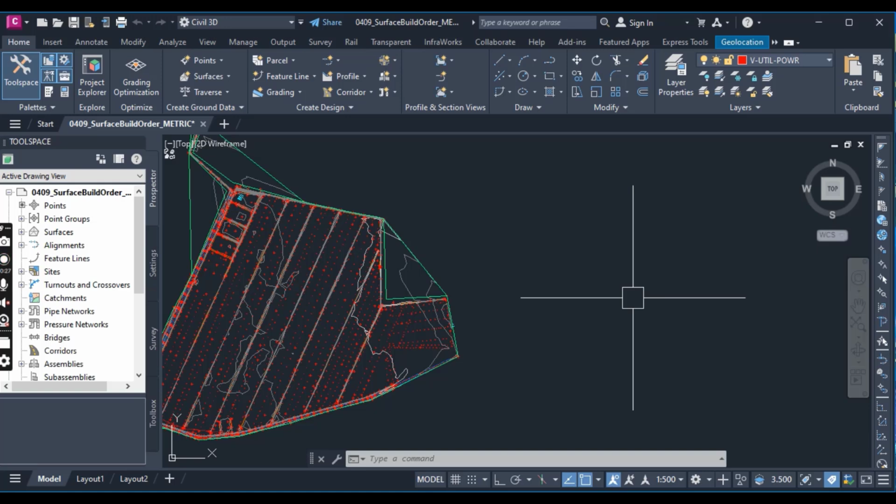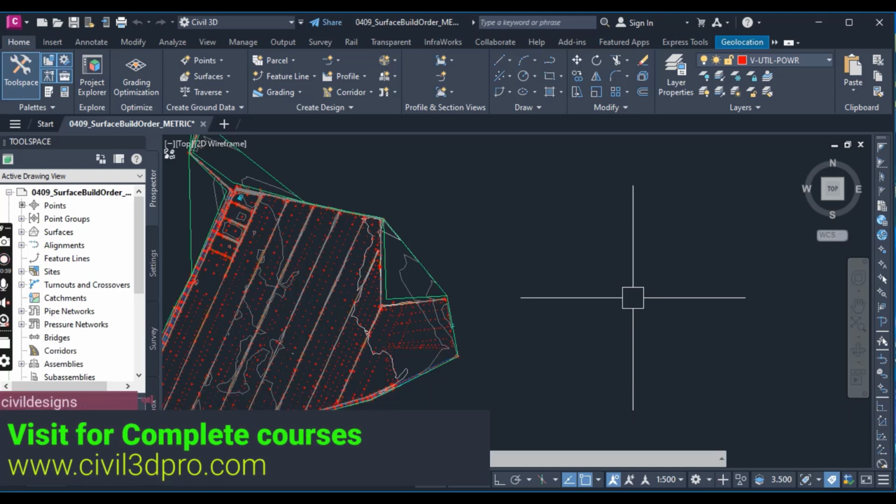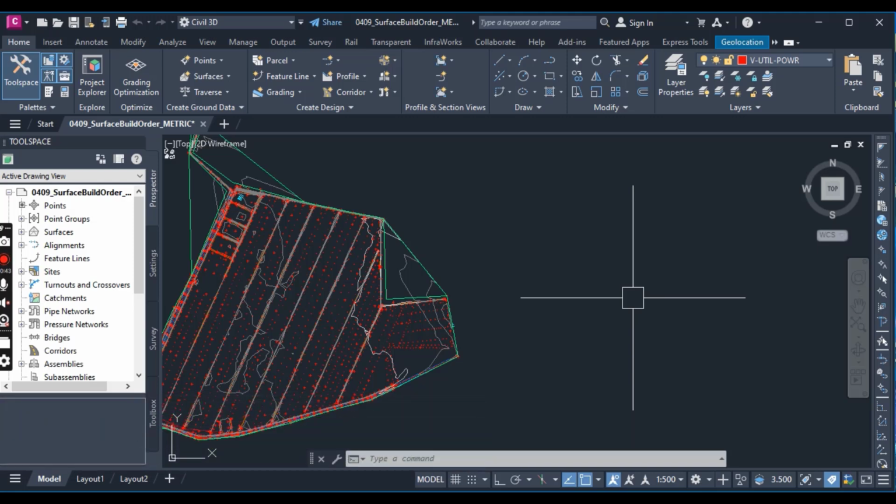group containing surface points, and then add breaklines delineating triangle edges such as the edges of pyramids, ridges and ravines. Lastly, boundaries are added to delineate the outer limit of the survey, edges of mounds or buildings. If existing surfaces are to be a blend of GIS contours and survey data, the GIS contours are added first.